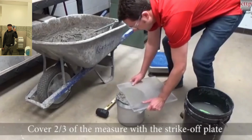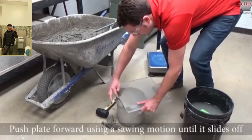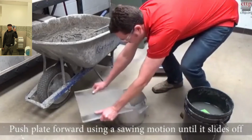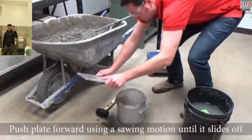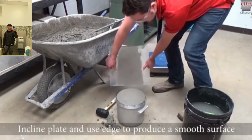Cover 2/3 of the measure with the strike off plate. Push the plate forward using a sawing motion until it slides off. Incline the plate and use the edge to produce a smooth surface.